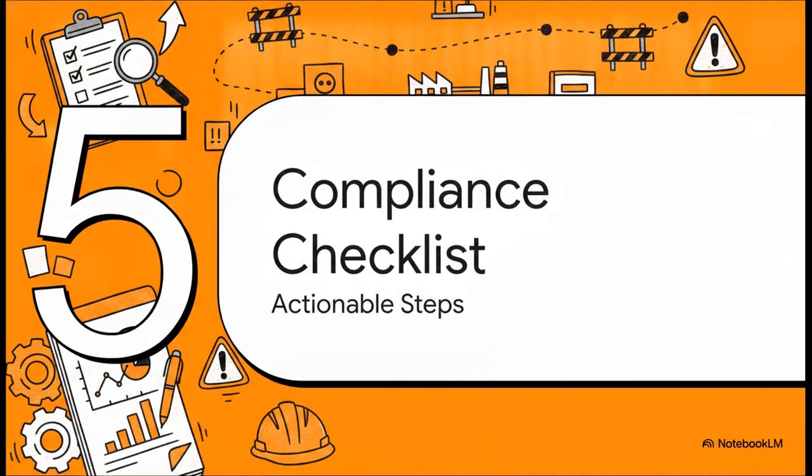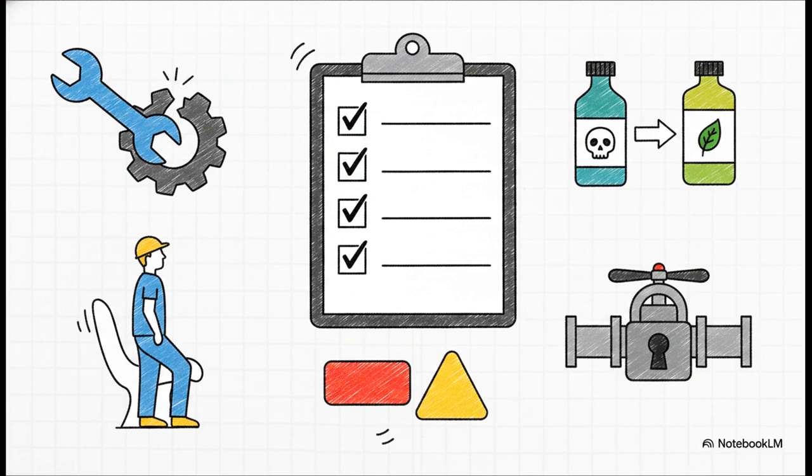Section 5. Your plant compliance checklist. All right, flip to the last page of your clipboard. Let's rapid fire through this compliance checklist to make sure we've distilled everything we covered today. 1. Always target engineering controls at the hazard source first, way before you resort to PPE. 2. Actively substitute toxic materials wherever possible. 3. Execute step-by-step ergonomic redesigns. 4. Deploy complete enclosures and electronic smart barriers when those hazards just can't be removed. And 5. Strictly separate your ANSI danger versus caution signage to preserve their psychological impact.